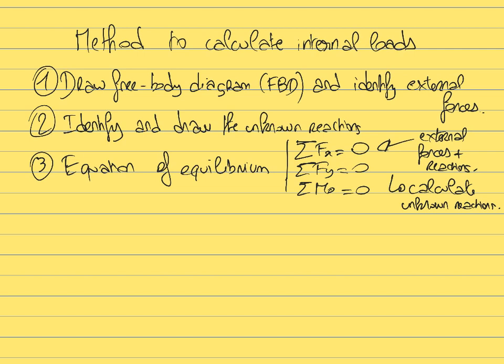Then we move to step 4. So far, what you have done is to calculate the unknown reaction, which is good, but our goal is to calculate the internal loads acting at a given point within the material. So for this, we need to use the method of section.